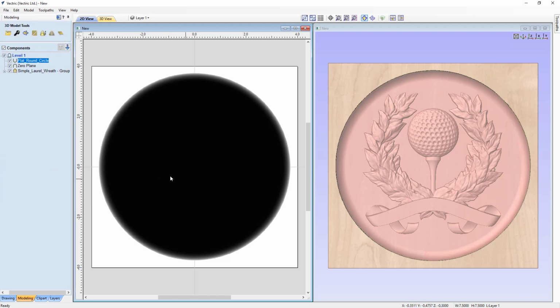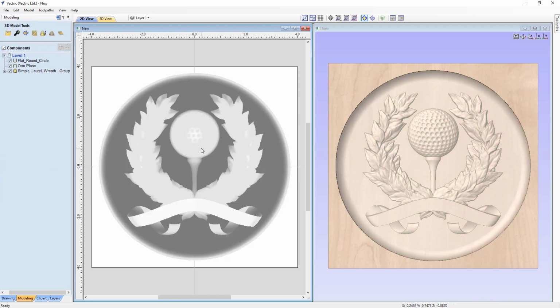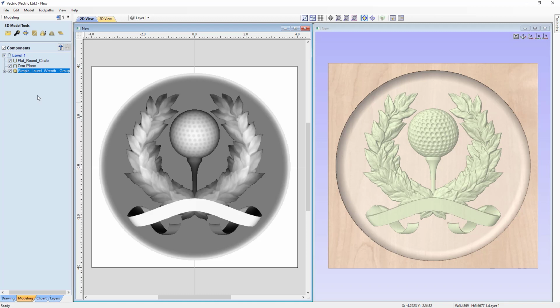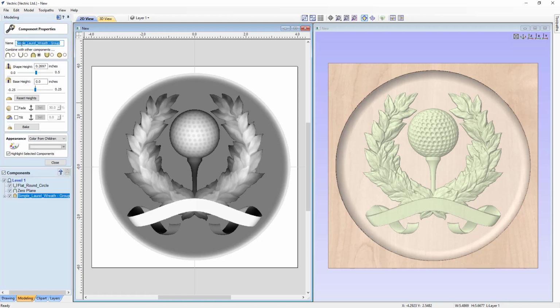And let's just go ahead and have a look at our actual layout here. Let's take a look at the components for that. And they're at 0.26. Now, one thing we're going to want to think about is we probably want whatever is inside of the dish to be slightly not proud of the surface of the dish, of our material, but fit nicely inside of our dish. So it needs to be less than, the shape height needs to be less than the depth of the dish. So let's change this to be 2.8. Press the space bar and take a look.